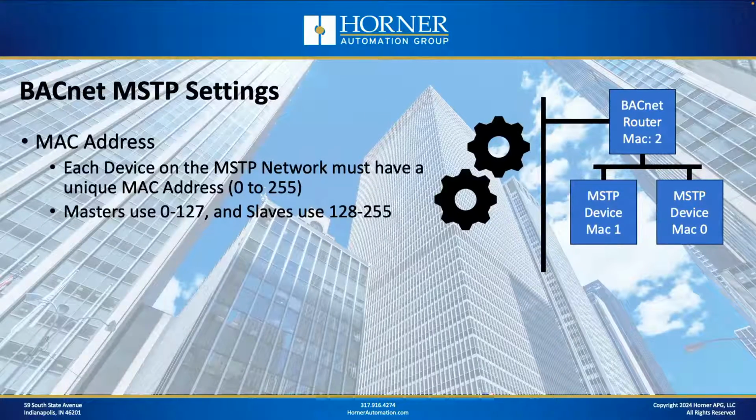Okay, now let's talk about some key settings that are important to know for BACnet MSTP, starting with what is called a MAC address. Now, in the Ethernet world, a MAC address is a unique address that's assigned by the manufacturer of the equipment. Completely forget about that. That's not what we're talking about here.